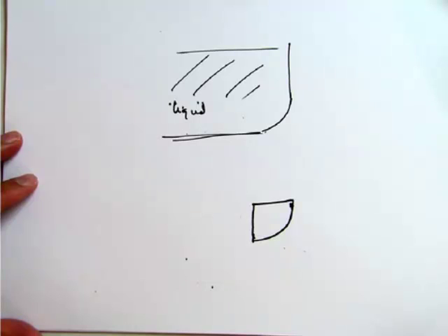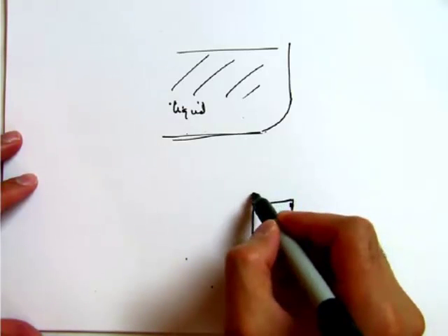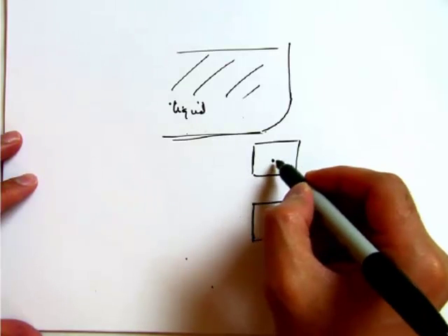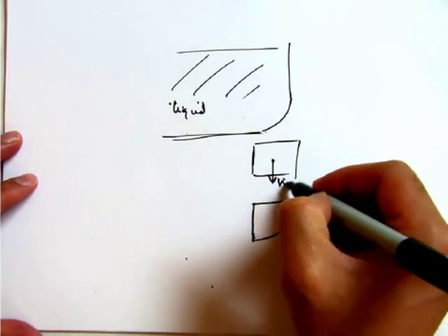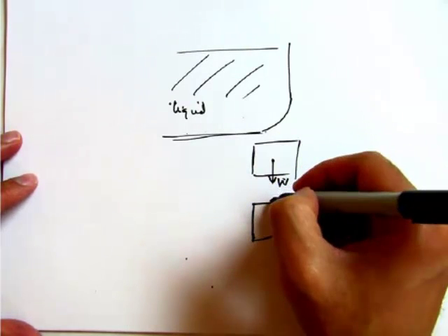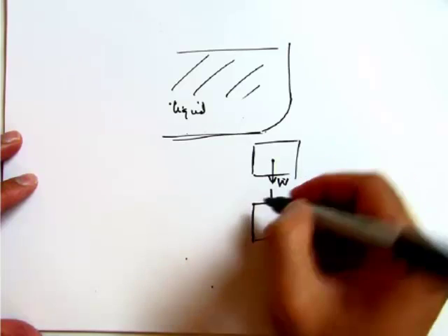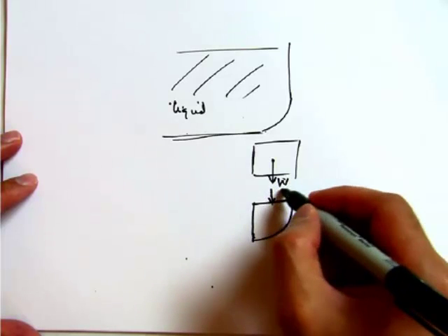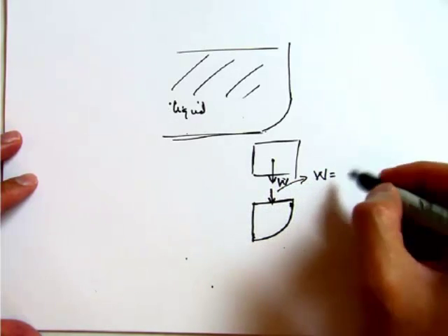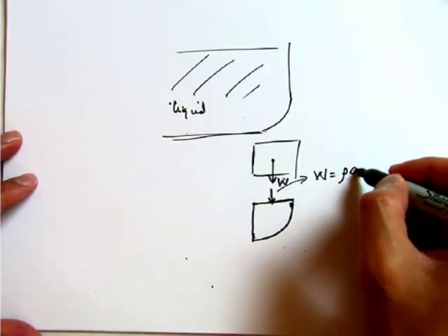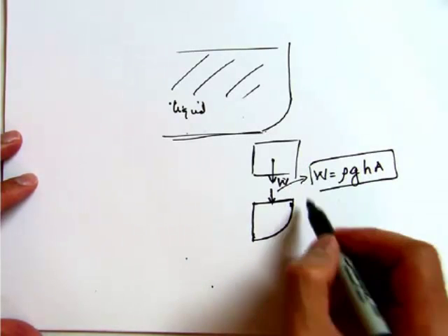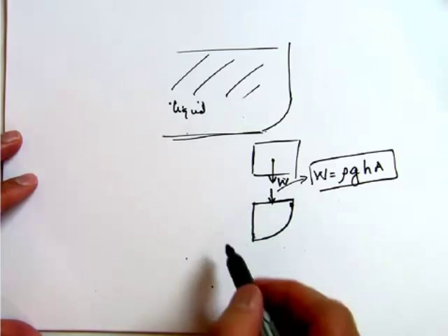Okay, and then you have some force acting on top of this. So the idea is there is some fluid on top of this. Alright, so there is the fluid, and it has some weight, so that weight is actually acting somewhere over here, around half of this line. That's where the weight of this fluid will be acting, which is simply rho g h times the area. So that will be the weight of the fluid that is sitting on top of it.